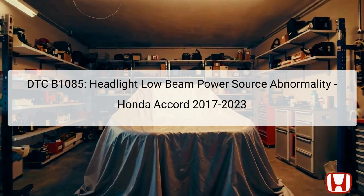The diagnostic trouble code DTC B1085 indicates a headlight low beam power source abnormality in the Honda Accord models from 2017 to 2023. This fault is related to failures within the headlight system, specifically within the relay control module, which is responsible for regulating power to the headlights.